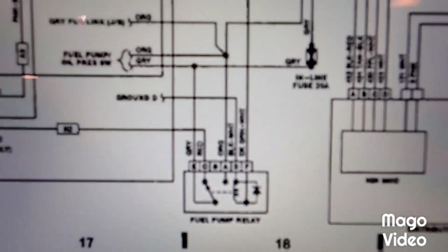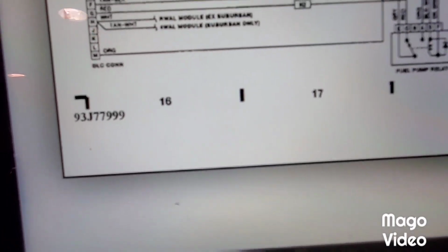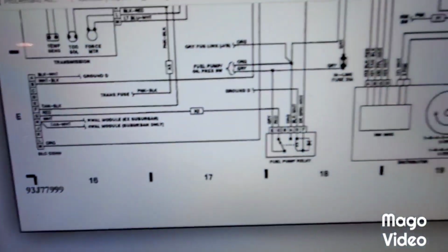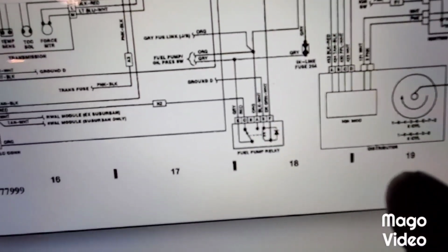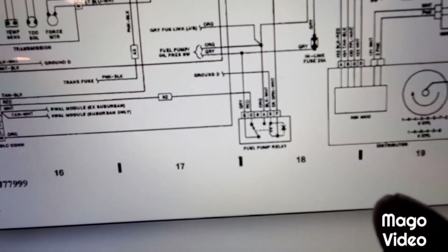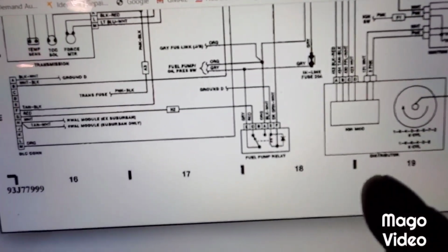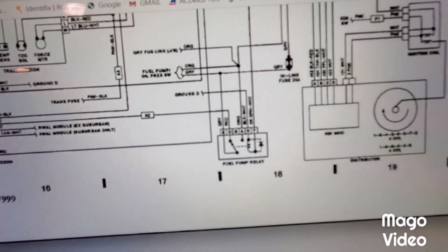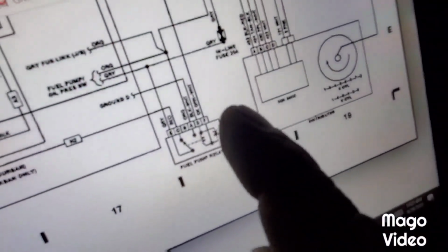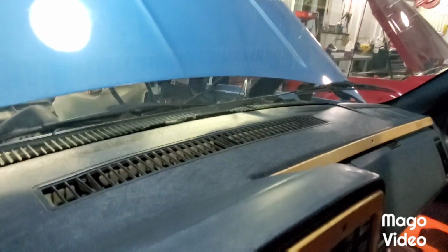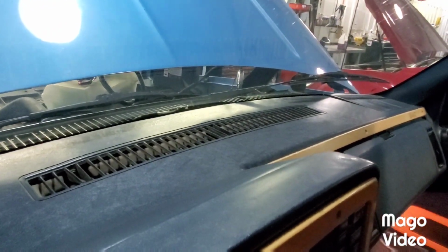Let's check for our switched power on the green. What color is it? Dark green white. Okay, which means we're going to have to switch the polarity of our 5 amp test light over to B negative. Actually, I'm going to switch to the 2.5 amp. I don't want to do 5 amps. Alright guys, I wasn't comfortable doing a 2.5 amp test light, so I just got my regular test light in there. Again, we're on the dark green wire. That would be the switched power from the ECU or the ECM to the fuel pump relay control side.